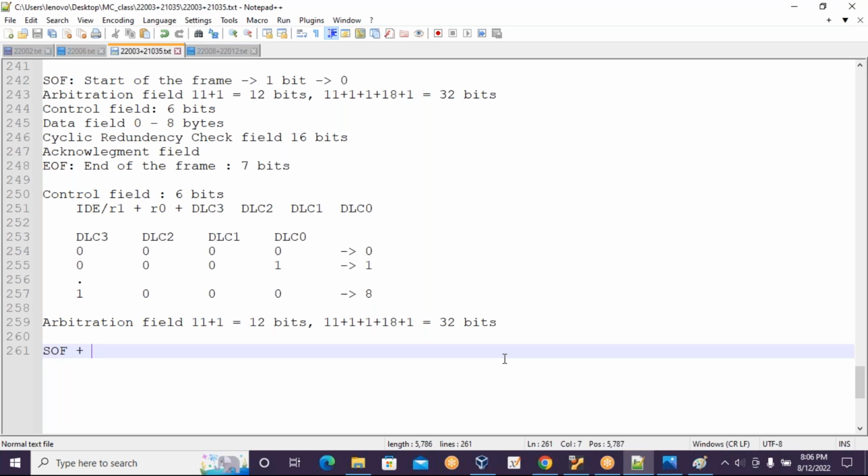Please answer. What were they expecting? What is the next thing I'm going to transmit if I have to start the communication? In I2C, I used to pass the unique address. Do I have a unique address in the case of the CAN protocol? No, we don't have a unique address. It is the identifier. All of the nodes in the network will next be expecting the 11 bits of identifier.